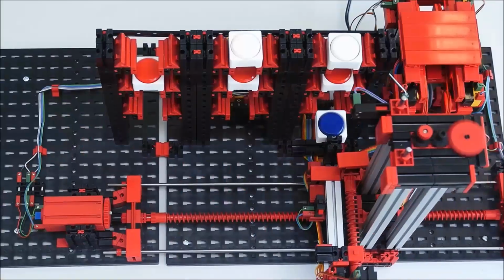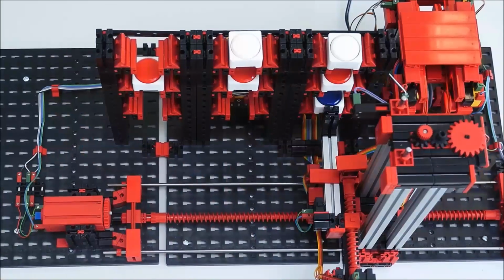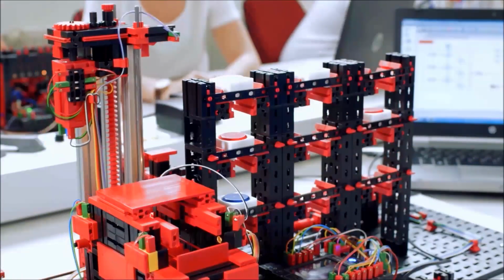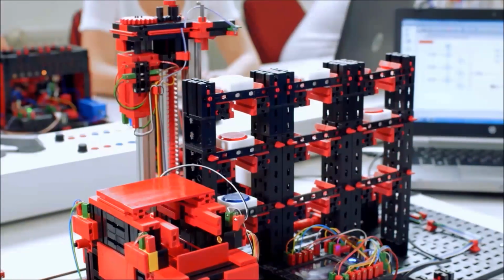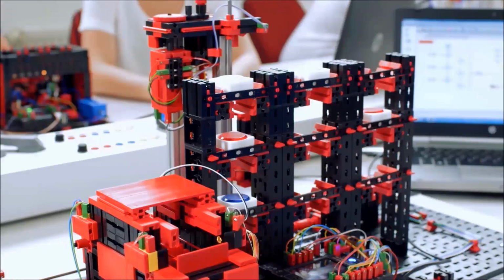Once again, the 24-volt version of the model has a relay board for motor polarity reversal and both a multi-pin connector, 26 pins with a grid of 2.54 millimeters, as well as additional PCB terminals with push-in connections for all inputs and outputs. Again, you will need to provide your own PLC and programming, and the 9-volt version, again, is pre-wired to a pre-programmed Robotics TXT controller, and one 120-volt power adapter is required.